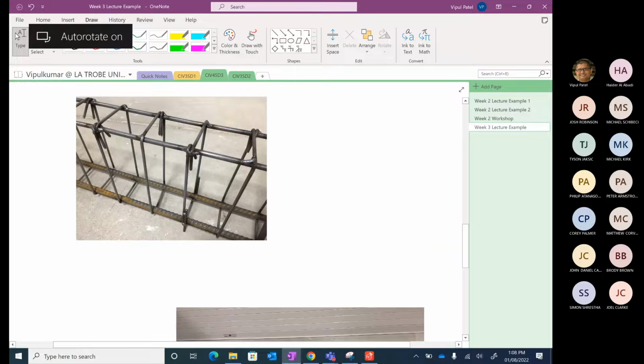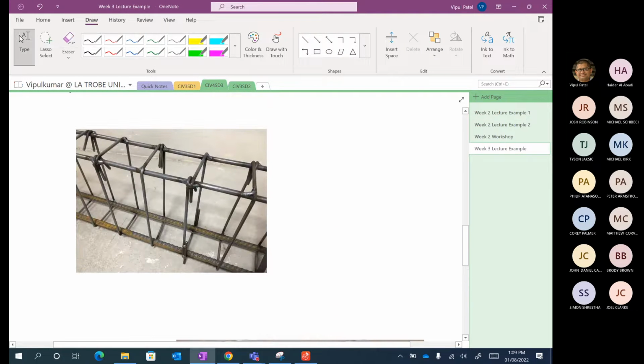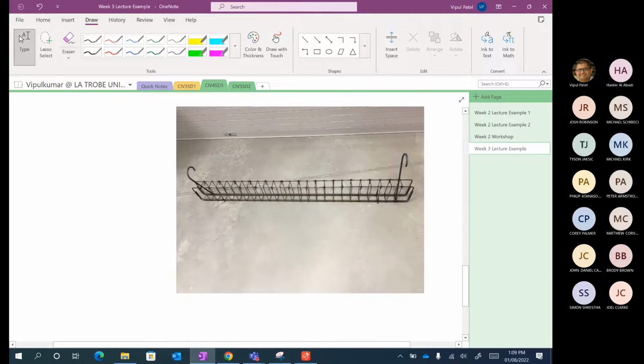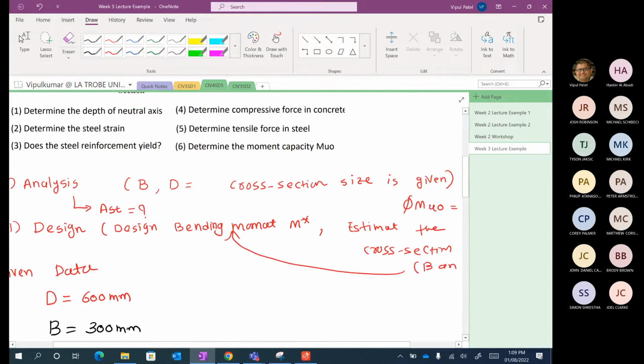So now this is the reinforcement that you can see here. These are your fitments, just the reinforcement. And in our case, it's given R10 fitment. R is again the ductility class, and 10 millimeter is your diameter for the reinforcement. Again, you can see this is the main reinforcement, longitudinal reinforcement or tensile reinforcement, and these are your fitments. So this is all good now.